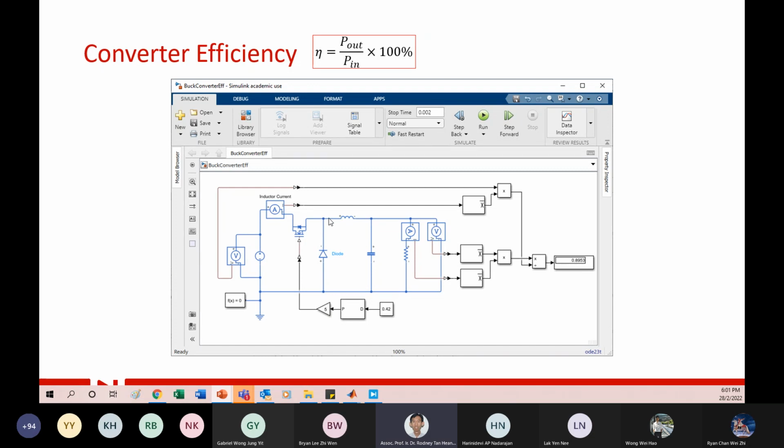So this is how the DC-DC converter comes into play. I showed you just now, when we use a normal linear regulator you bought from the shop, 7805, the efficiency is only 51%. But now with just a simple design, you can go up to 89% efficiency.